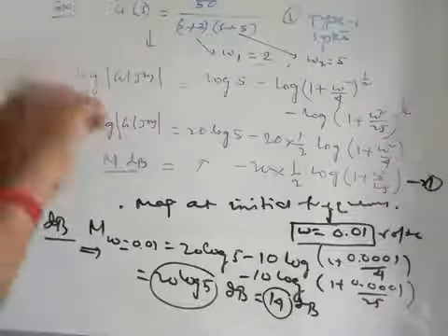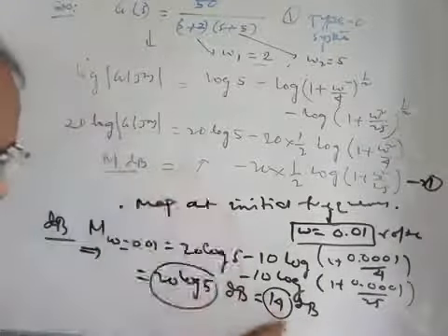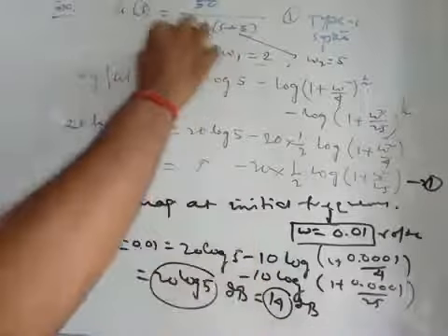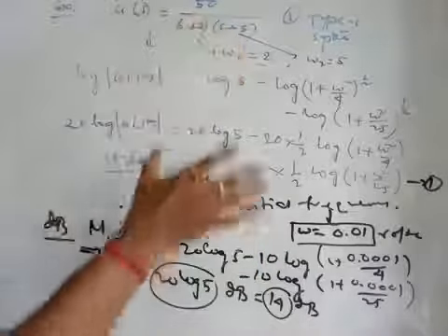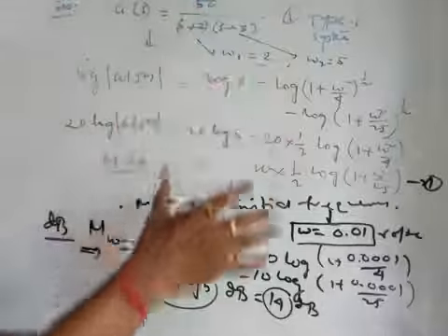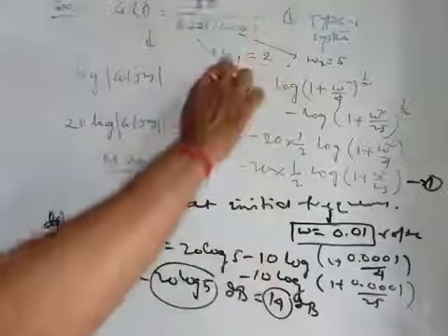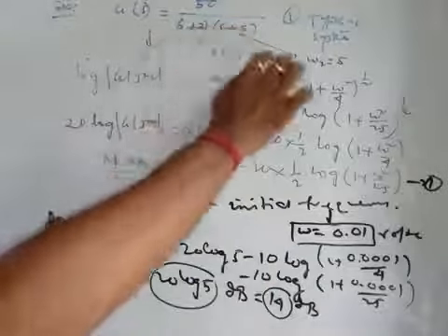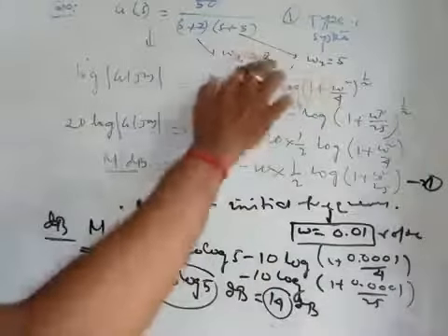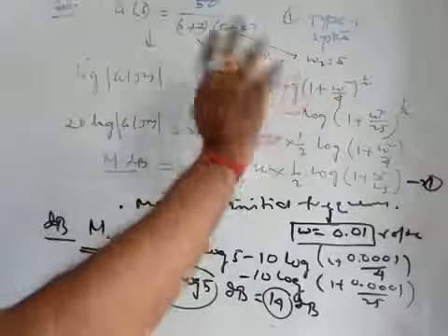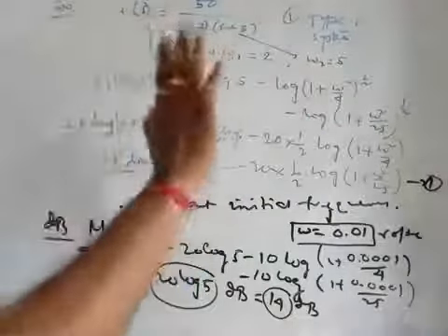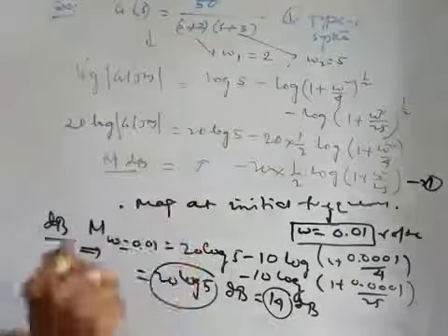Now we will see why this value is required, because we have taken the example of this kind of system, and we will try to draw the complete magnitude plot corresponding to that, right? So this is a type 0 system where each of the two first order factors will have the corner frequencies omega 1 and omega 2, right? And there are no zeros here, only the poles, right?